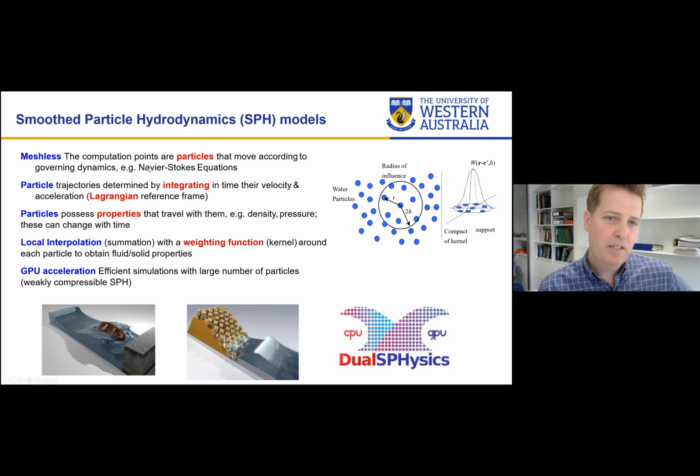It's fundamentally not different than any traditional CFD modeling approach, but the main advantage is it's meshless. So it's still solving the Navier-Stokes equation, but instead of having a fixed grid like we're generally used to with models, we have essentially nodes that are based on defining parcels of water that are defined by mass, and defining a kernel region where we're looking at things like gradients and so on by looking at how this occurs over these neighboring particles. So the particles travel with the fluid motion, and their properties change with time.